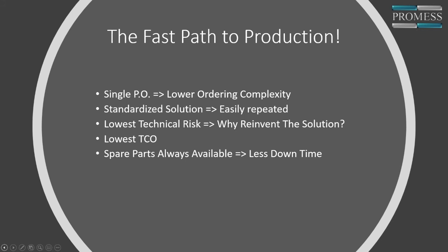Can one system measure static and dynamic? Yes, that is possible. Typically, our customers will choose one way or the other, but there's no theoretical reason why you can't do that. To do that, you're typically going to use a 2-axis Ultra Pro controller, meaning you're going to have 2 torque units, for example, one on the input and one on the output. Through our controller, you can have one hold position and not move at all to do it statically, and then enable the other to put a resistive load on to do it dynamically. So it'll typically require a 2-axis system to do something like that.